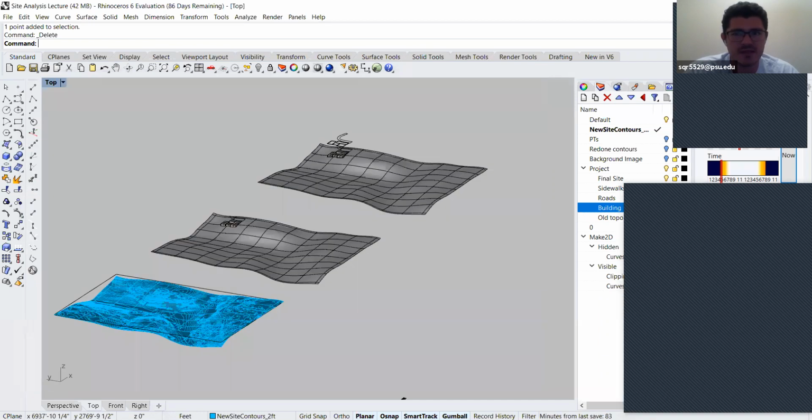So you can see SketchUp. If I draw any random rectangle and I draw a line and put it even 10 feet in the air, and it's a ridiculous contour, and you want it to snap to all this, if you go to Draw, Sandbox, From Contours, it will snap to all those lines and fill in the void. So even whatever ridiculous plug you're making for your site, it will snap to it, which can make it a little bit easier to work with. But Rhino has more functions and different methods of drawing.